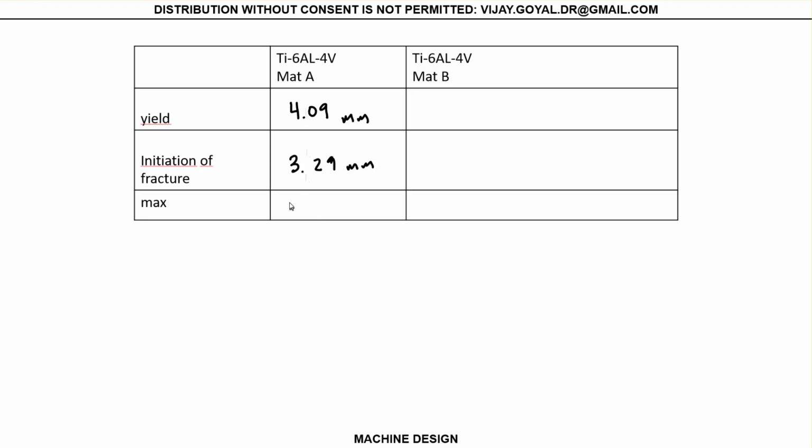And the maximum thickness that I would use for your design, for your selection, you always choose the maximum from these two. So if you want to be safe in both cases, if I choose this, it's not safe here. But anyways, I know that this was going to be driven by yield, and the reason I know that is because A was smaller than AT, and it was bigger than 0. I knew that. So I could have just started the problem, done the yield, and stopped right there without having to do extra calculations.